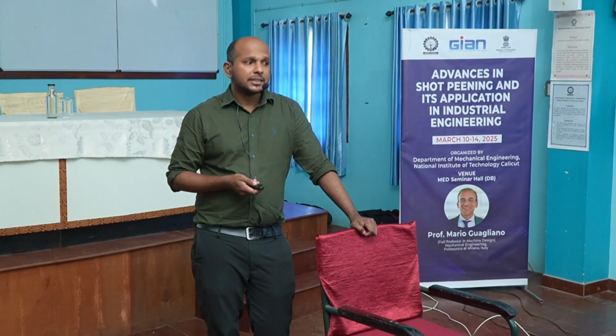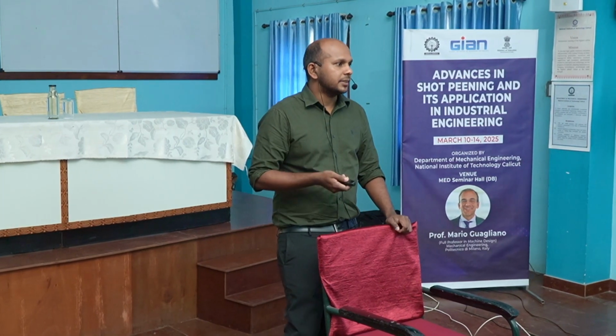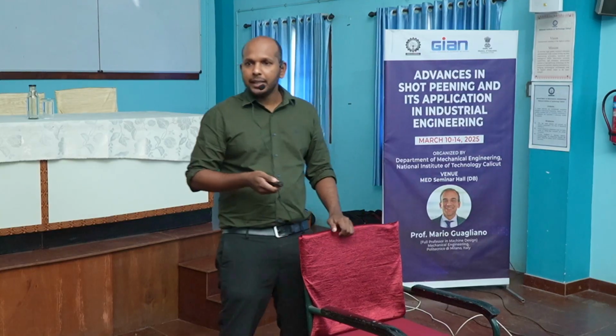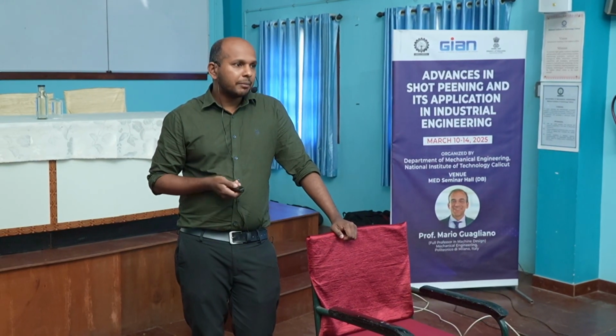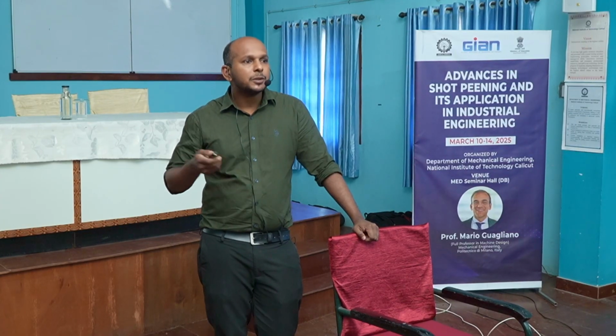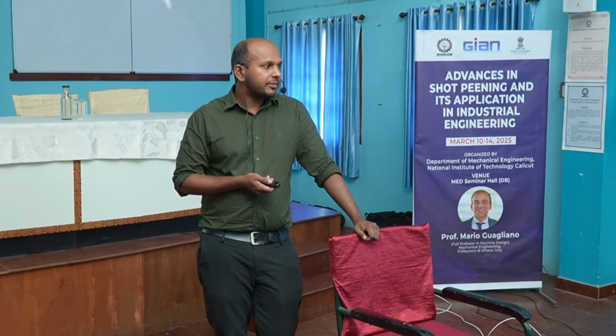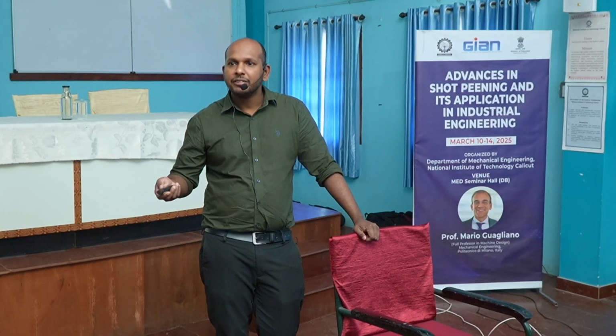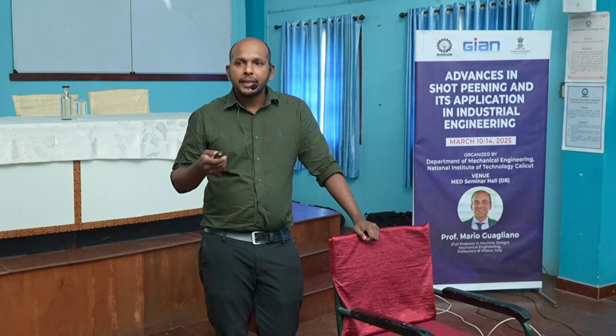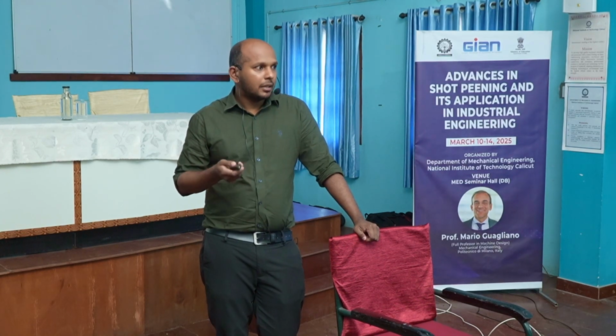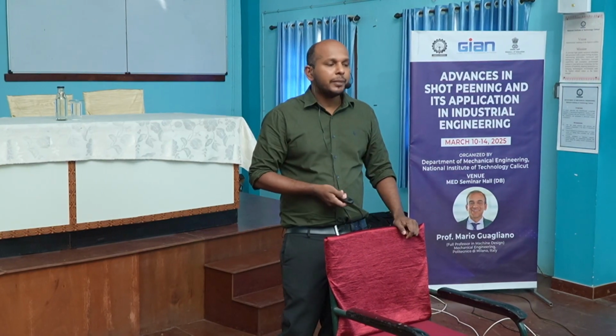And what is the difference between a mechanical and chemical treatment? By mechanical means we will be modifying the surface. In chemical treatment, chemical reactions are involved. By means of chemical reaction, we will be modifying the surface properties. And coming to electrochemical processes, there will be electricity involved and also chemical reaction involved. The synergistic effect of this electricity and chemical reaction will further modify the surface of this material. Then there is case hardening. Plasma nitriding and carburizing all come under case hardening. Okay, so our shot peening comes under this mechanical